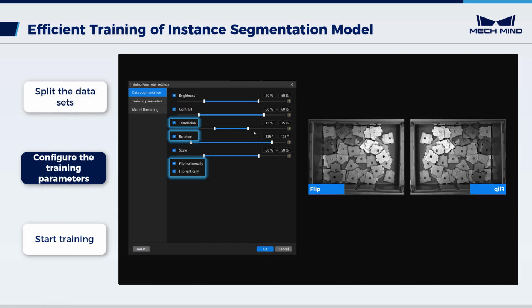In this scenario, top layer workpieces in the bin are randomly stacked. Even similarly exposed parts may vary in position, orientation, or flip. Thus, adjust these parameters appropriately to retain key features and ensure the model recognizes all symmetrical and varied poses.